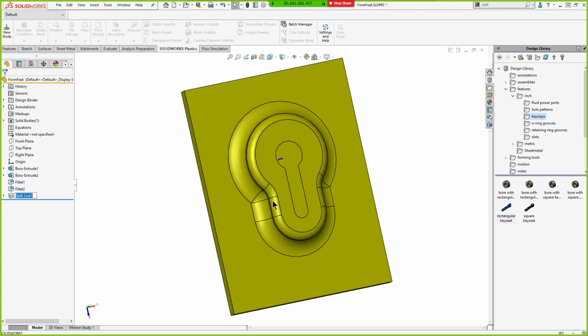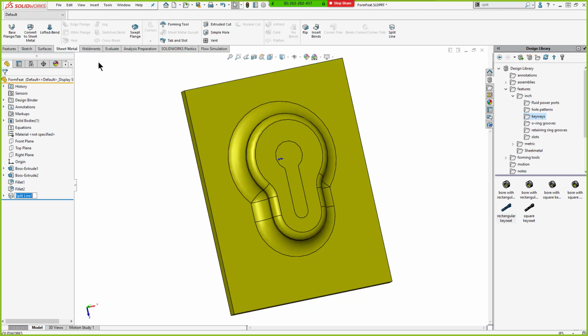And so this is, again, the concept that I'm going for is reuse. If you know you have a sheet metal vendor that has this specific stamp, or maybe it's a good idea to find out what they have in stock for tools. That way they don't have to go buy a tool to make something that you designed. Instead, if you design around the tools they currently have on their shelf, you can take advantage of them.